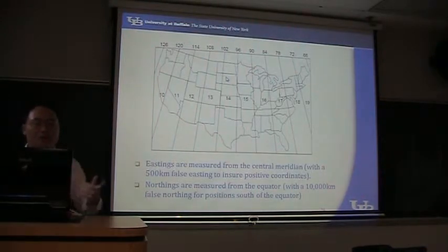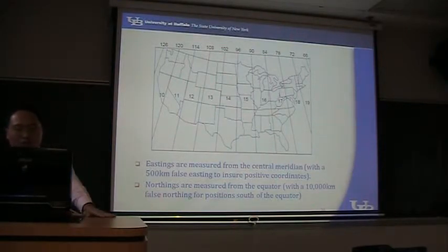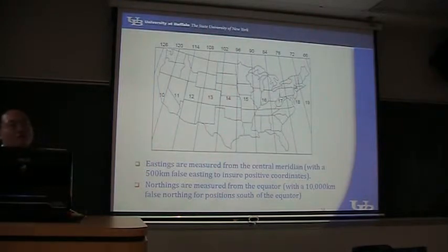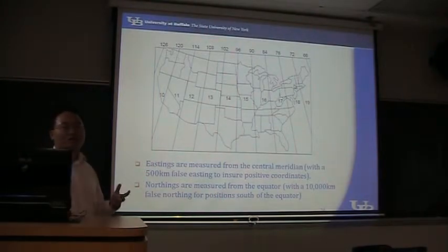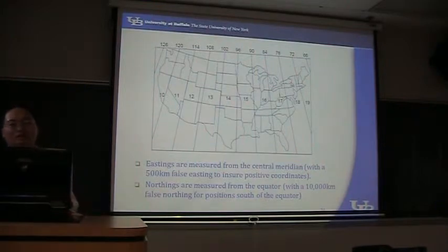And when we use the UTM system, we take a look at the US mainland. Now we have a major question. Which zone, which UTM zone are we in? 17. We are here, right? We are here. This is Buffalo. This is New York City, and this is Albany. But most of the time, we get a map that is located in UTM 18 because they are made by somebody not in our area. So very often we see maps with UTM 18.